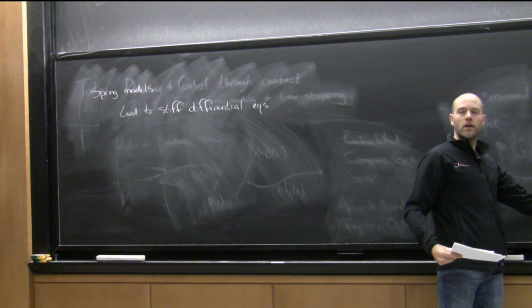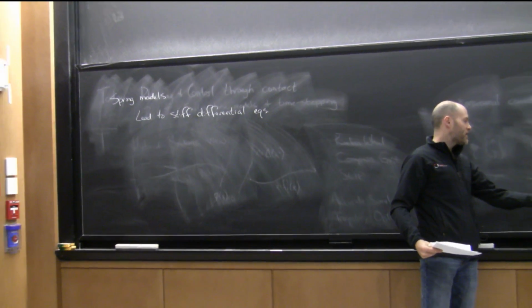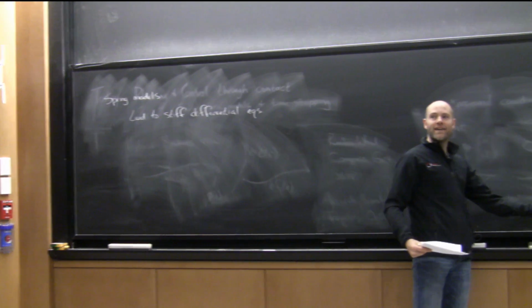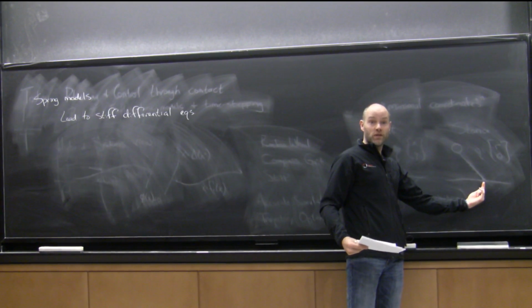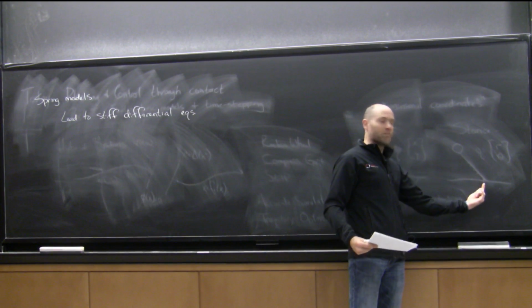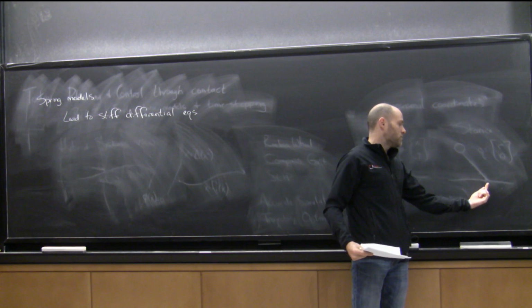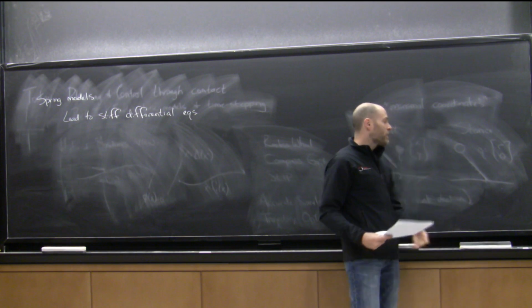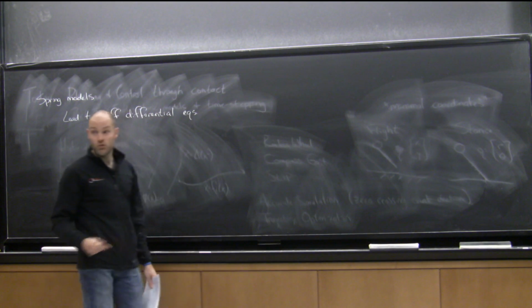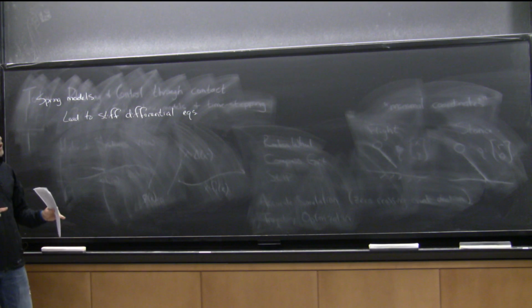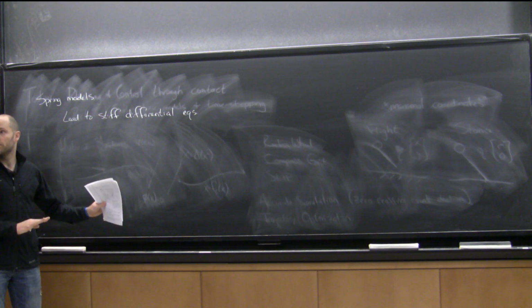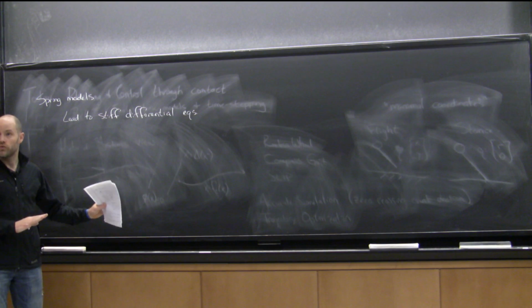We thought of that not as a soft constraint with high gain, but as a hard constraint, which we could solve away with our Lagrangian mechanics by just writing a pin joint there. It sounds fancy, but we can solve away with our mechanics, and that made a difference numerically. You can do that in the maximal coordinates too. And that's what we're going to do, okay?